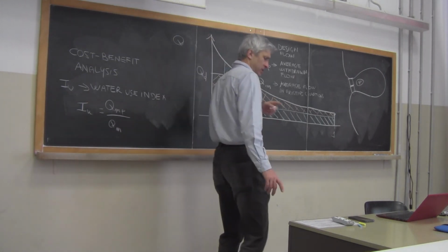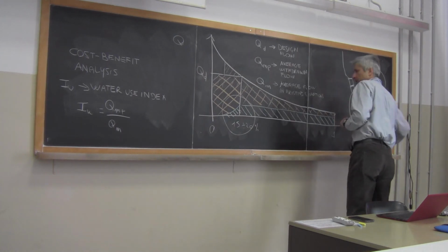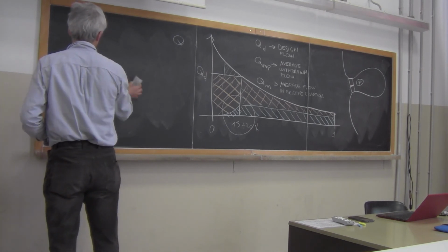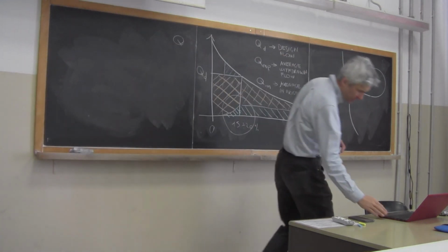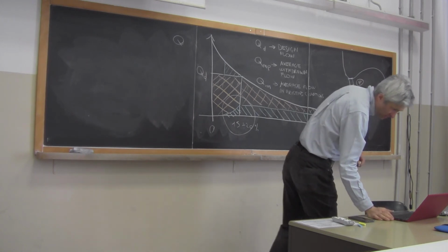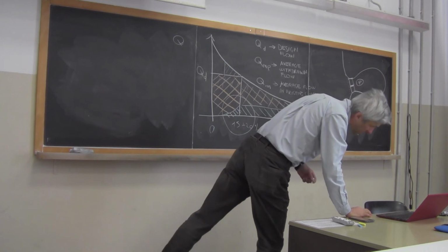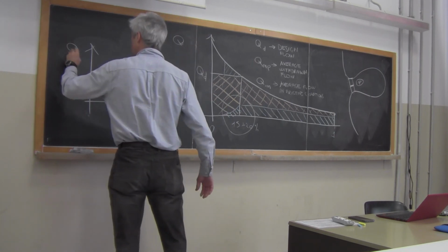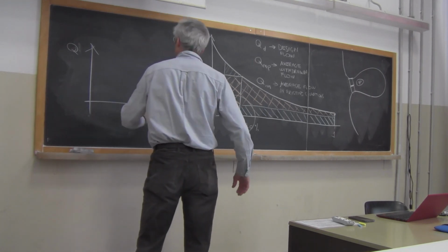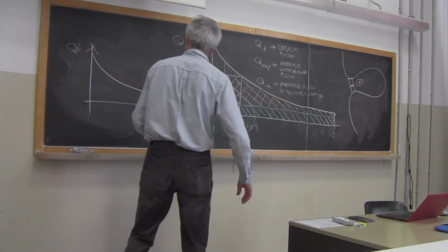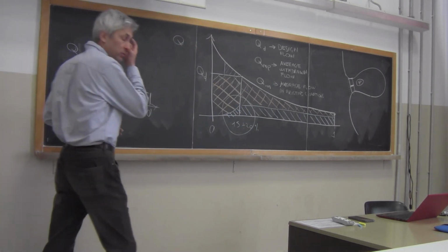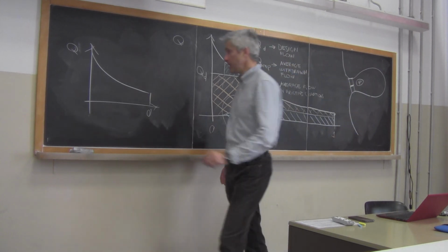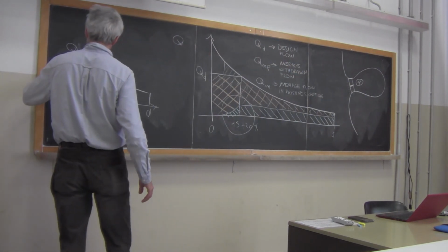And what is interesting, it's included in my slides, there is a figure which shows the flow duration curve. Let me look at the figure because I want to make it similar. Okay, there is the flow duration curve, which is something like this. Q and D is something like this, more or less. It's more articulated than you will see, but it doesn't change the meaning. And then there is the design flow of the hydropower plant, which is something like here.